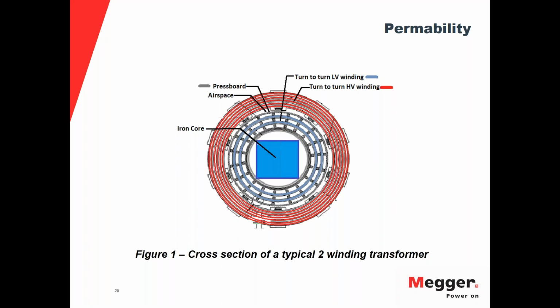With that being said, power transformers require gaps between the core and the associated windings, as we mentioned earlier, for cooling purposes, whether it's air or oil. And the tighter those windings, and you'll see the difference between a large transformer and a small pad mount transformer is how tight the windings are, which is equivalent to a lot better mutual inductance and better coupling.